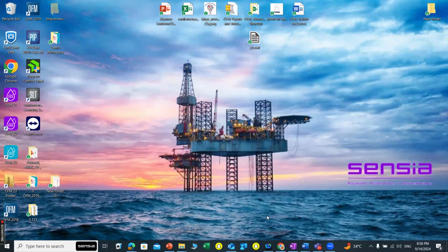Yes, in most of my projects I'm using PipeSim at the same time. Why? Because sometimes you don't have a test, like you don't have the pressure at the bottom, the flowing bottom hole pressure. It's not measured. So you have to use PipeSim to estimate the pressure, right? You have to use PipeSim to do another analysis, like sensitivity analysis: which choke size, which artificial lift I should use to improve my production. So PipeSim, of course, will help.